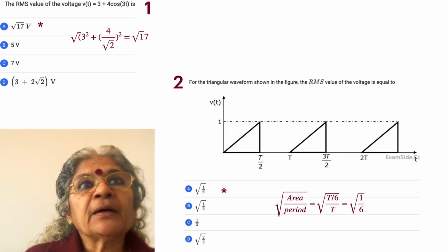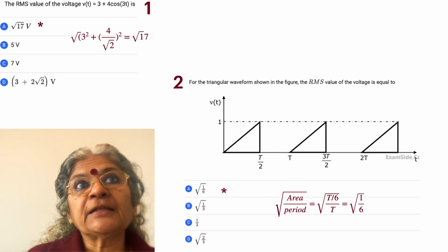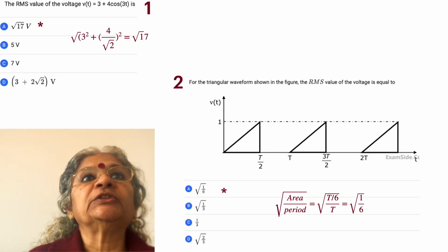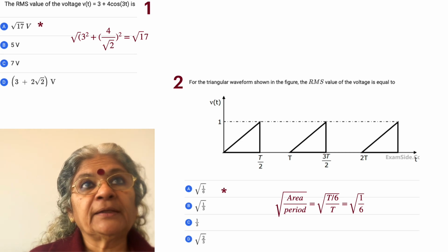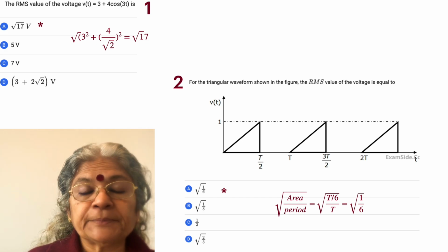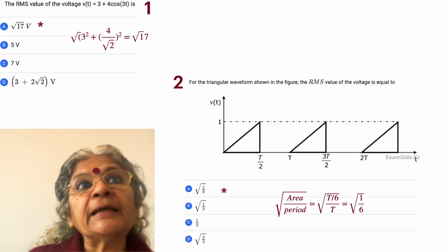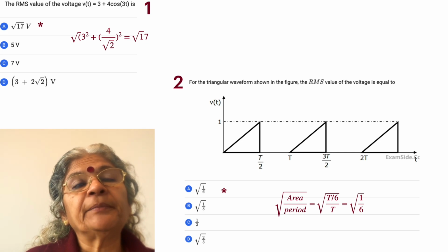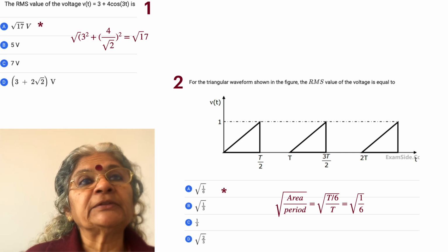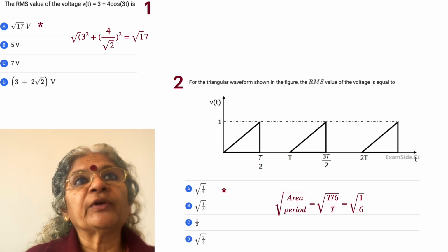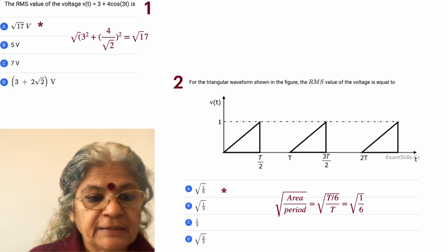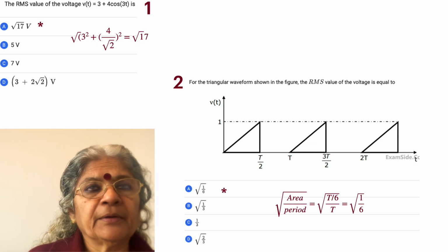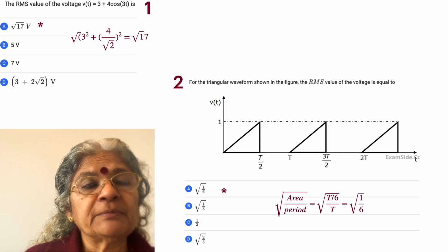Why? Because only for periodic signals you have power associated with them, and RMS is normally associated with the heat or the power that a waveform can produce. And hence they have what may be called as infinite energy. Okay, so infinite energy means finite power as per Parseval's theorem, and so we are fine with the periodic signals here. So in this case, we see that it's a very easy way of dealing with such problems.